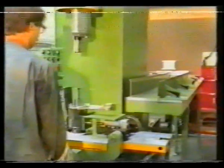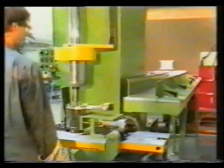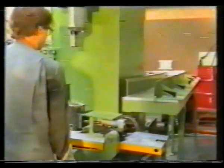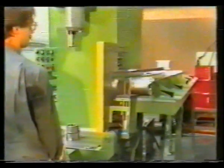In a simultaneous secondary operation, the mandrel is ejected and at the same time, the runner is trimmed off the rotor which has just been cast. The press table tilts 90 degrees, transferring the finished rotor to the discharge ramp.